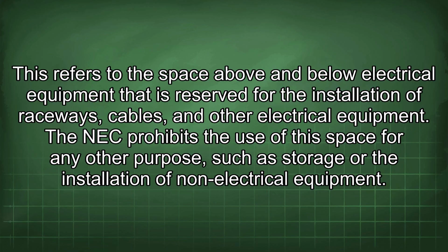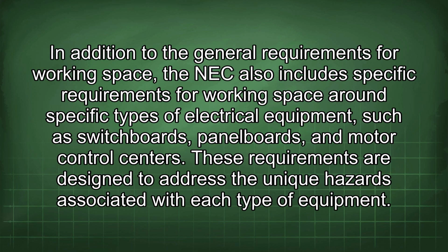installation of non-electrical equipment. In addition to the general requirements for working space, the NEC also includes specific requirements for working space around specific types of electrical equipment, such as switchboards, panelboards, and motor control centers. These requirements are designed to address the unique hazards associated with each type of equipment.